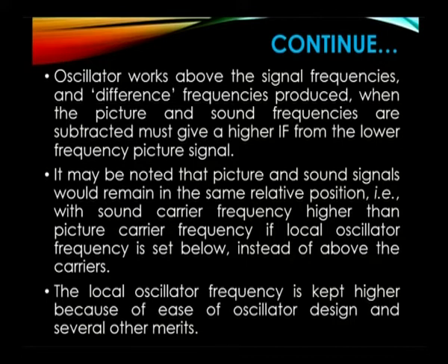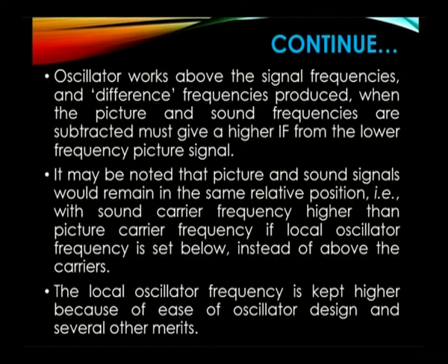If the local oscillator frequency is set below instead of above... the local oscillator frequency is kept always higher because of ease of oscillator design and several other merits. That is why the local oscillator should be higher than the carrier frequency.